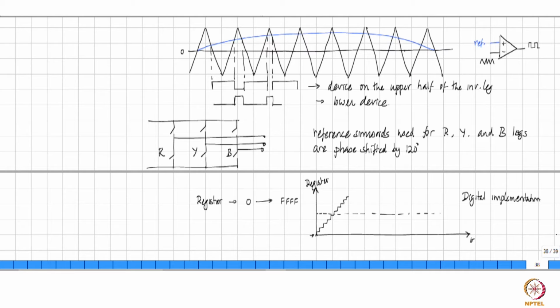As the rotor is going to rotate, the EMF value also goes on becoming different, and therefore you cannot operate this machine without knowledge of the rotor position instant to instant. In the earlier case, it was sufficient to know at one instant, then you only need to know where the rotor is when the EMF begins to change again, right? Until that time, you know that it is fixed, therefore there is no problem.